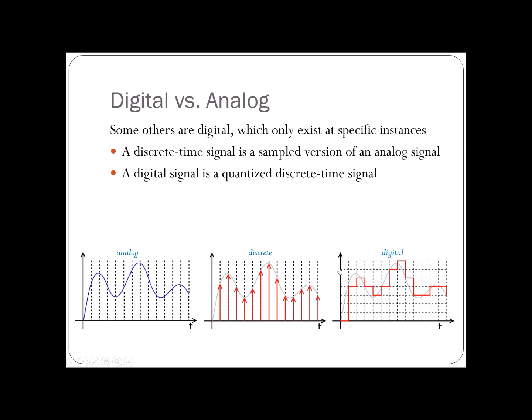If you are wondering about the leakage, then yes, the signal will leak. Some information is missing, that's right. Same as when you move from an analog to a discrete signal, what happened in between the sampling times is missing. You don't have the information between the times when you sample the signal.